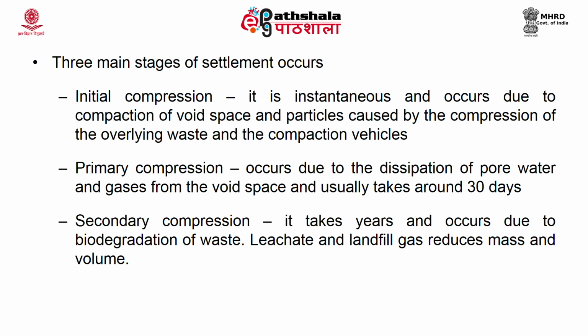In the secondary compression, it takes years. This is a very slow process and it mainly depends upon the biodegradation of waste. It takes years and occurs due to biodegradation of waste. During secondary compression, you can find the generation of leachate as well as gas, which will also reduce the mass and volume of your waste.